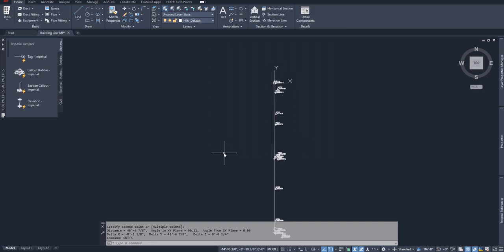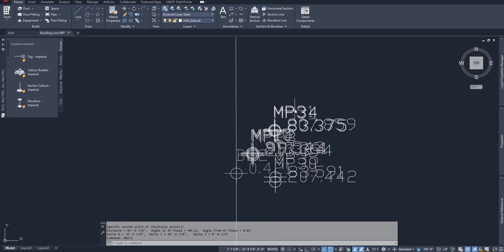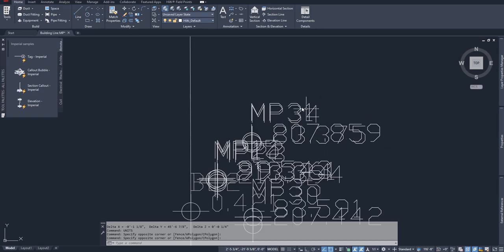After your units have been established and you know that all the points are showing up dimensionally correct, now we get into the editing of the way that these look. One thing that you need to be aware of is that these come in as blocks. So if I highlight over this, you can see that this is a block reference called Hilti Default for the software that I was using on my total station.